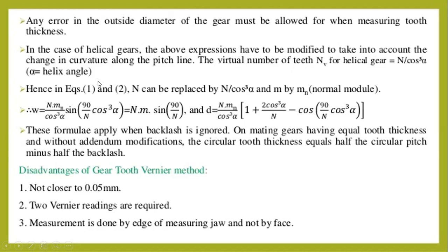And the virtual number of teeth, NV, for helical gears is taken as N by cos cube alpha, where alpha is the helix angle.